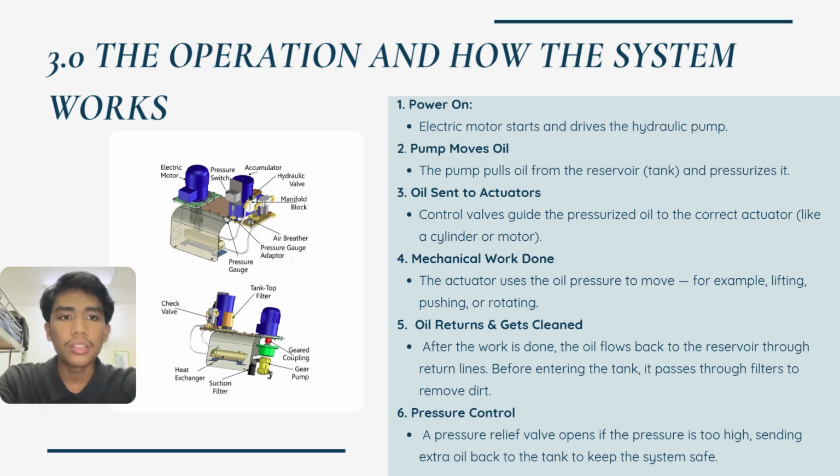Then the oil returns and gets cleaned. After the work is done, the oil flows back to the reservoir through return lines. Before entering the tank, it passes through a filter to remove dirt. And the last point is pressure control. A pressure relief valve opens if the pressure is too high, sending extra oil back to the tank to keep the system safe.